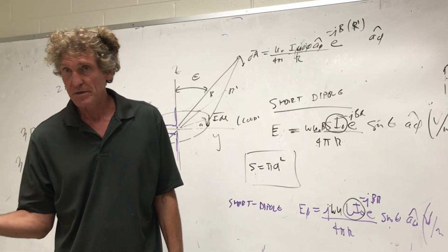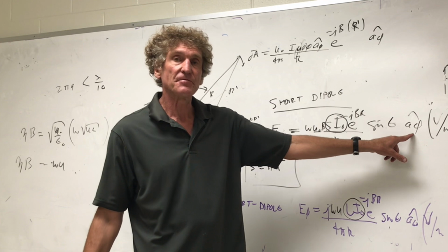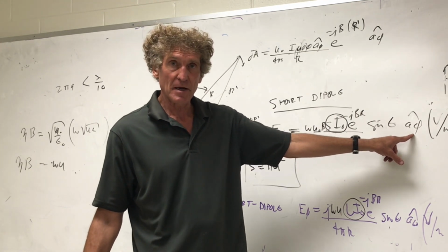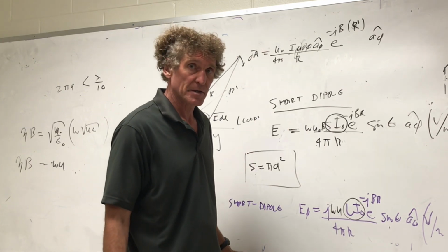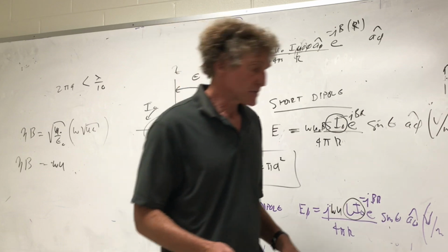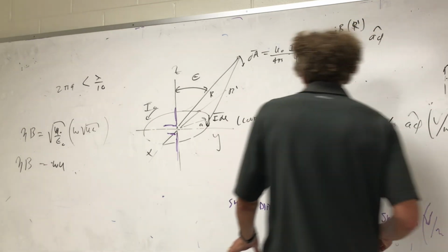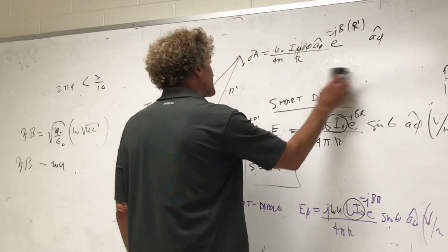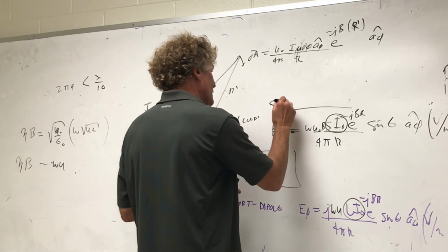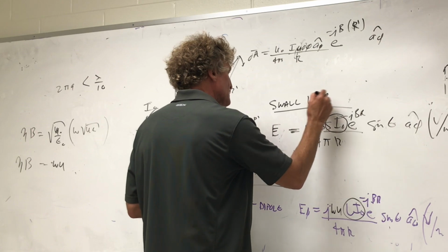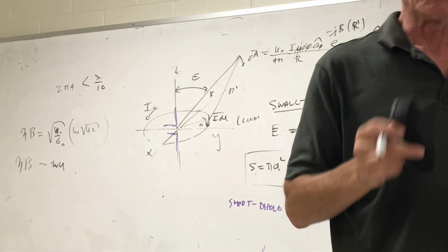I'm just showing you some of the things that I see. Same exact shape. The difference is obviously this is in the phi direction if it's in the xy plane. This is in the theta direction if it's in the z-axis or perpendicular to the xy plane. The gain is the same for this one. For a short dipole, I'm sorry. This is a small loop. I put short dipole. This is a small loop. Keep me straight if I make mistakes. A little sleep deprived. All right, sorry, that was for the small loop, but you all see that, right?